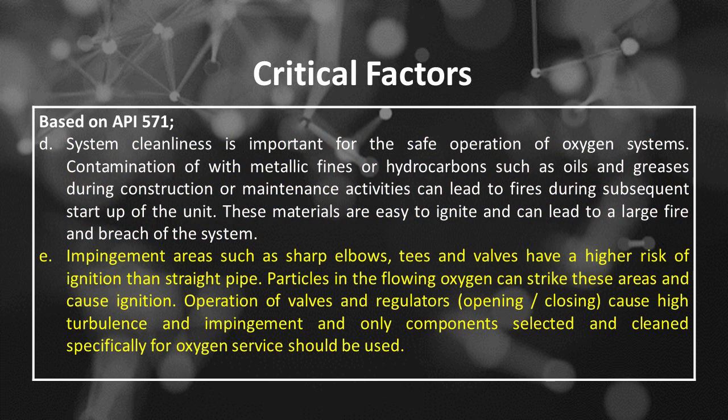Number E, impingement areas such as sharp elbows, T's and valves have a higher risk of ignition than straight pipe. Particles in the flowing oxygen can strike these areas and cause ignition. Operation of valves and regulators, opening/closing, cause high turbulence and impingement, and only components selected and cleaned specifically for oxygen service should be used.